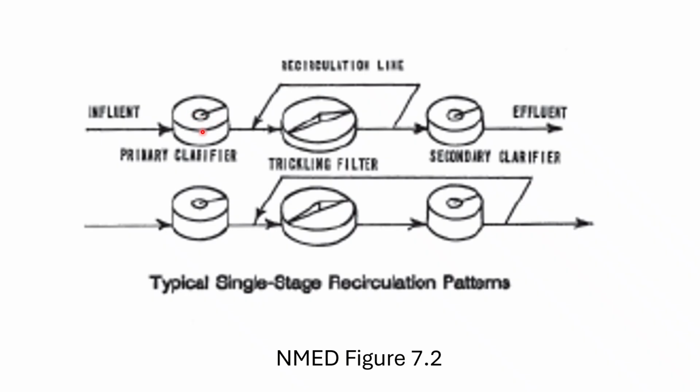We've got the heavy sludge and inorganics settling out in the primary clarifier. It hits the trickling filter, and that primary clarifier effluent becomes the influent for our trickling filter. The wastewater is trickled over that media, typically rock for a standard flow or plastic for a high flow, and we're going to have that slime layer, those microbes, metabolizing the BOD in this filter, the effluent from the primary clarifier coming into our filter.